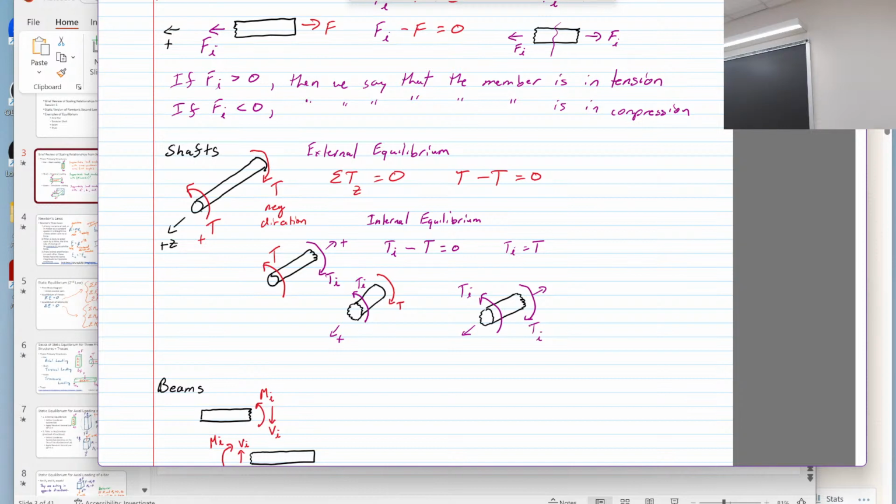I think the most straightforward way to do it is to take one. So in this case, we're looking for the force BC, right? So that's between B and C. So here, take a slice, and then you can have a choice. You can either use the slice and open to the space on the right, or you can open to the space on the left. Then what you're doing is you're using the external forces and that one internal force to figure out. You can just make basically an open force with those, right?